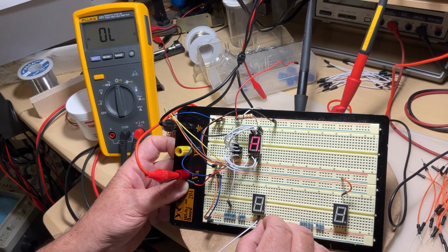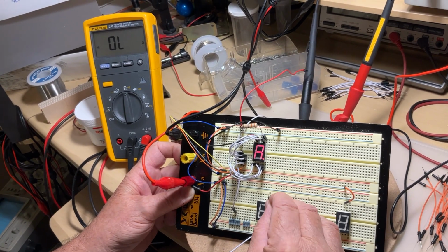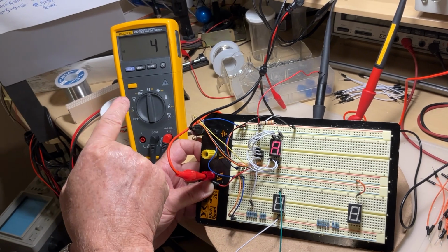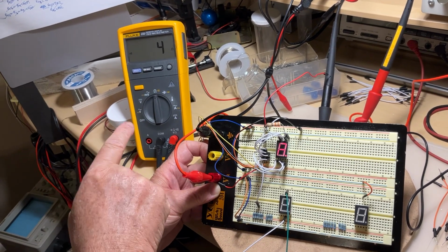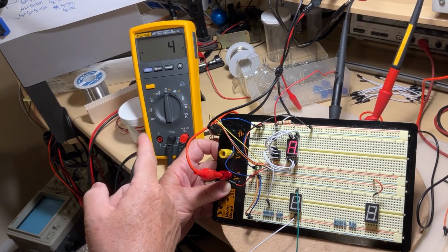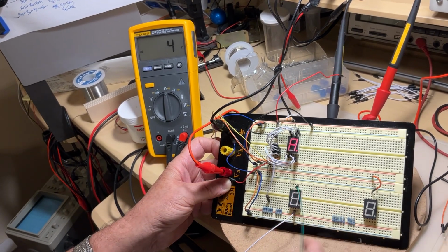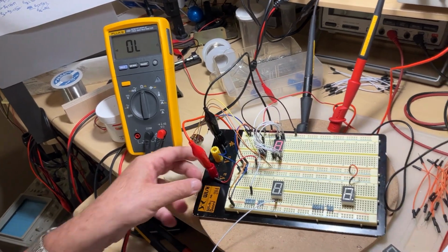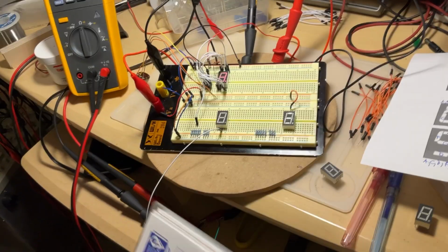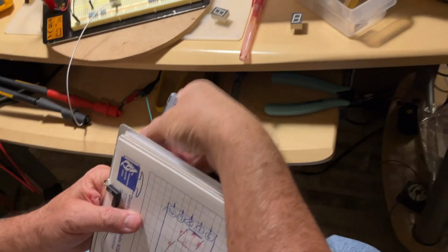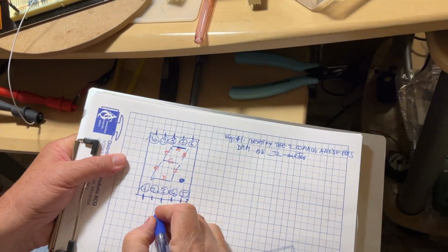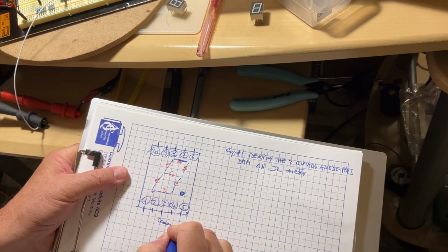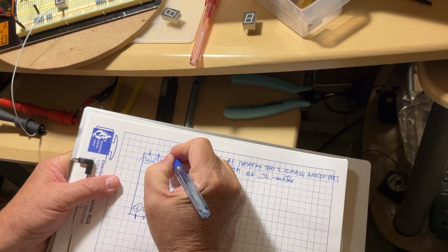Pin 4, pin 5, pin 6, pin 7, pin 8. Hey, take a look. It's a low value in ohms, it's not overload anymore, and I can hear the sound. So I just identified pins 3 and 8 are both representing the common. Here is a common, and here is a common.